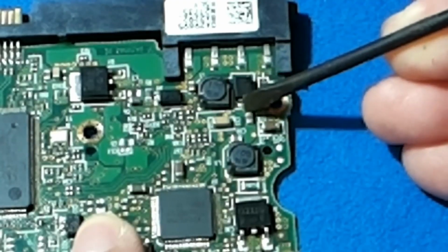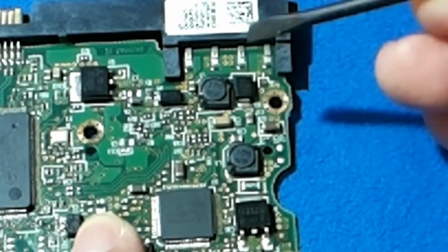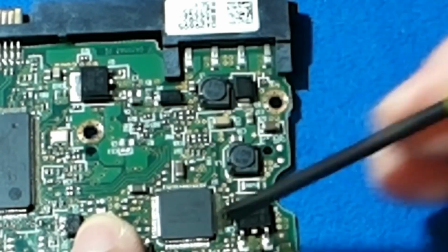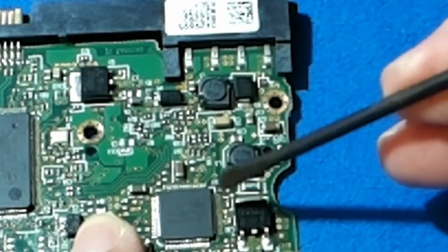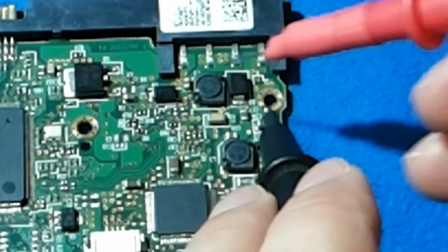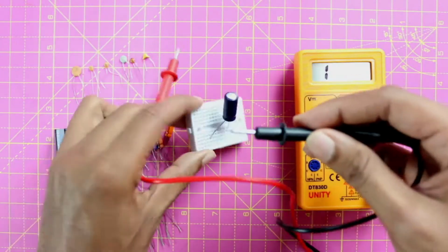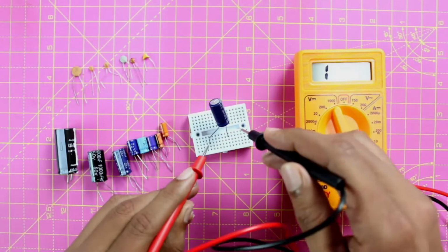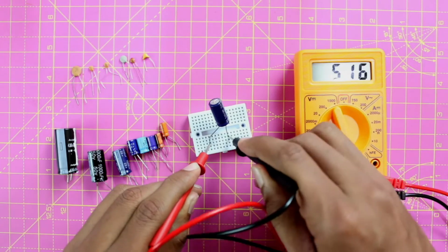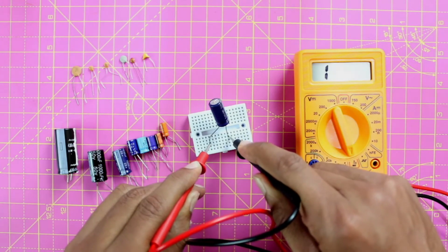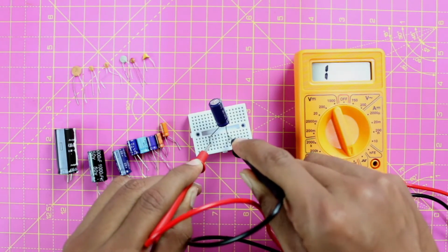If a capacitor is identified as short-circuited, it could impact the entire array, necessitating a thorough examination of each capacitor. This process might involve lifting one side to ensure accurate measurement. Utilizing a multimeter effectively significantly boosts measurement accuracy. Mastering this tool is imperative for anyone engaged with electronic components and circuits.